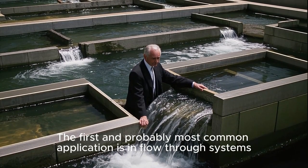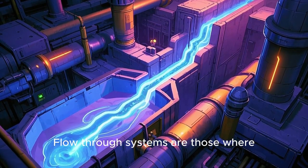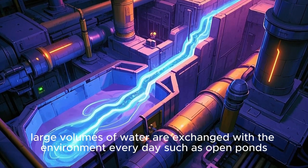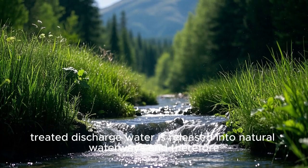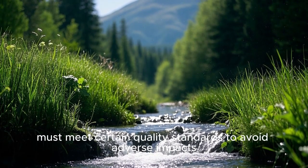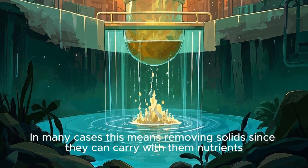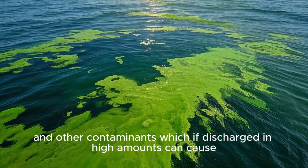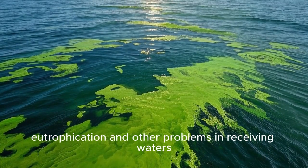The first and probably most common application is in flow-through systems. Flow-through systems are those where large volumes of water are exchanged with the environment every day, such as open ponds, raceways, or flow-through tanks. In these systems, treated discharge water is released into natural waterways and therefore must meet certain quality standards to avoid adverse impacts. In many cases, this means removing solids since they can carry with them nutrients, organic matter, feed, and other contaminants which, if discharged in high amounts, can cause eutrophication and other problems in receiving waters.